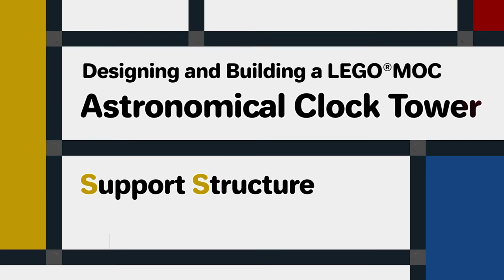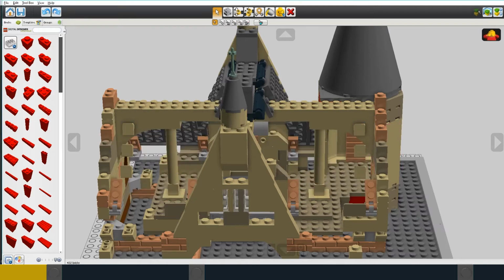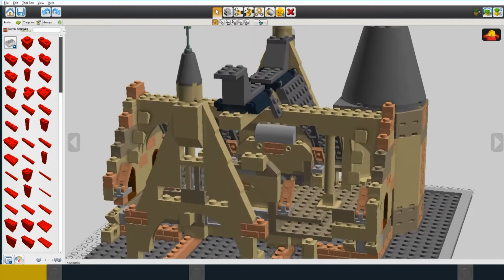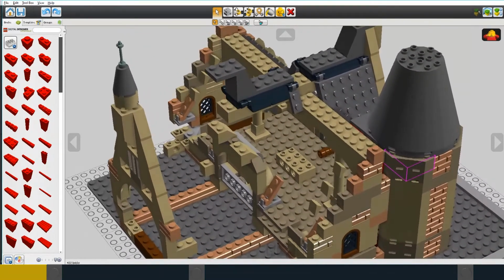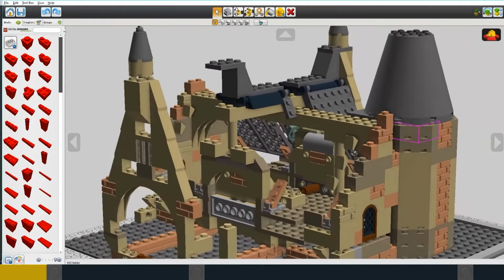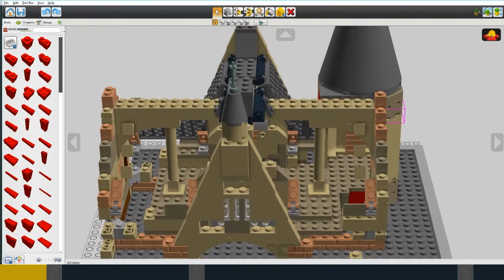Now, I think the roof and the internal floors may need some additional support. The beam forming the ridgeline of the roof is supported by the gables, but it's quite long and will need some support along its length, especially as it's supporting the ridge of the cross roof. I can use arches, columns or cross beams for that. Where I use a column or an arch, then it needs to be supported by something underneath to take the weight down to the ground.